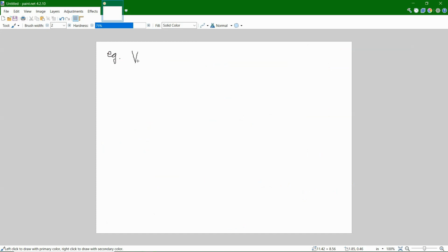So let's say my incoming voltage was 120 volts and my primary current is 7 amps. That's not area vector, that's 7 amps. And the number of turns in the primary is 3. There's no units, just 3. And the number of turns in the secondary is 12. Let's calculate VS and IS. I found this on the web.